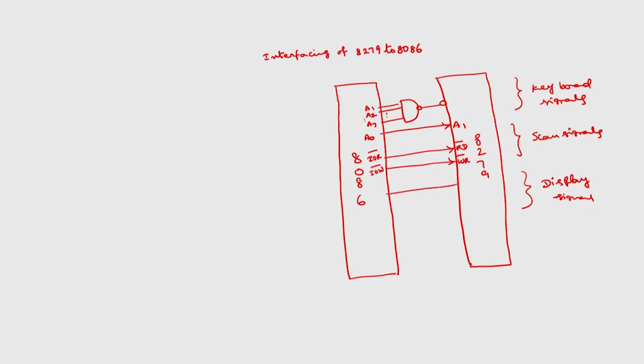Then we have clock signal, reset signal. This may not be directly connected, here we require some sort of clock division network, because of the operating frequency, you can use the clock divider to generate the clock of this one.